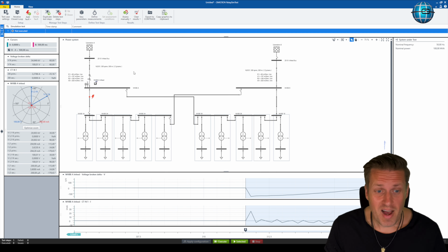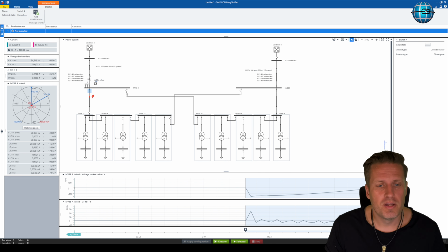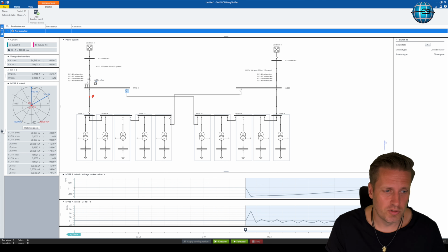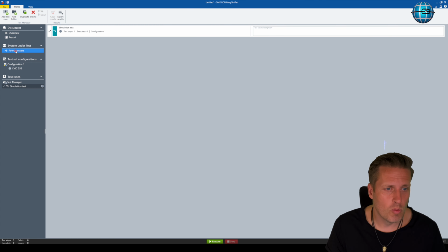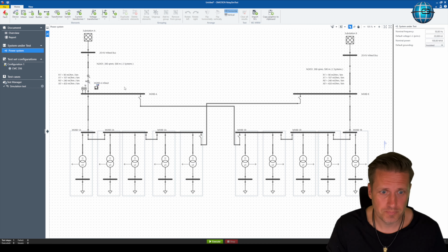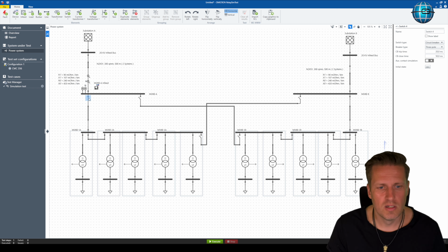Okay. And now we want to see what happens if we add another relay here and another relay here, and if we look a little bit deeper into the grid. For this reason, we go back to our power system. We already have the voltage, so all we need now is to add another relay which measures this 3I0 zero sequence current.